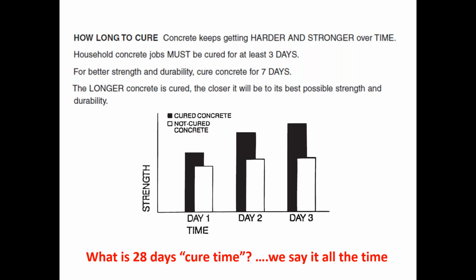And over time, as it's curing and hardening and all of that, the alkalinity drops from 14, to 13, to 12, to 11, to 10, etc. And generally speaking, at about 28 days, and this is a very loose statement, it's dropped down to a lower alkalinity or pH, around your 10s, 11s, and that's when you can paint it.